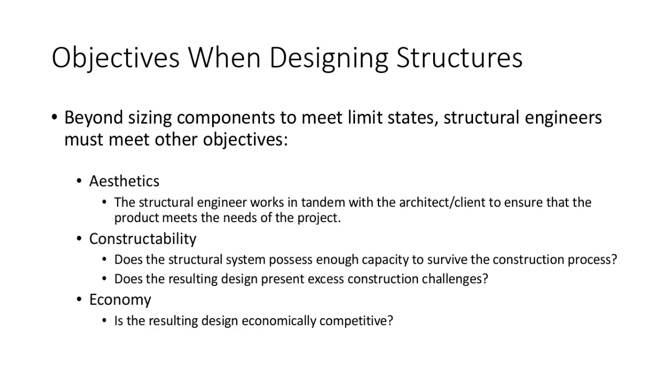If we're talking about, let's take the engineering building. We would think that constructability and economy is important, and yes, it's true. But the cost of the structure, the steel skeleton, the concrete slabs that hold this building up, is probably about 15, maybe 20% on a bad day of the cost of the entire building.